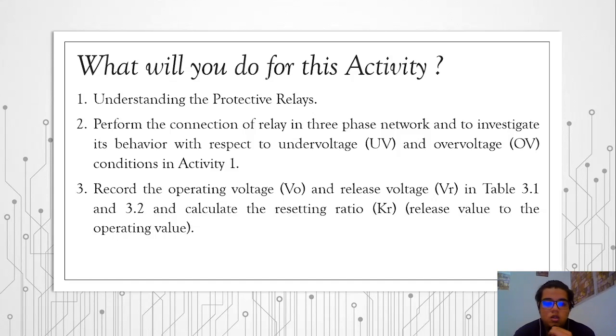Then we record the operating voltage, which is VO, and the release voltage, VR, in tables 3.1 and 3.2, and calculate the resetting ratio KR, which means the release value over the operating value.